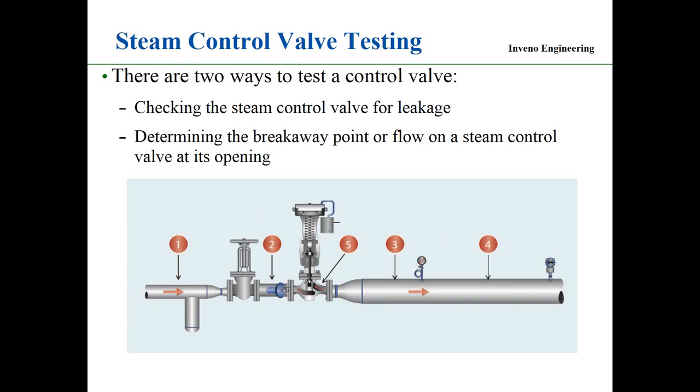Because I'm starting to set up a PID loop. And the PID loop assumes 4.0 milliamp is 0, no flow, and 4.4 milliamp, there is flow. If I have a dead band down here on the PID loop, the valve doesn't start to pass steam until 4.8 milliamps. It does start to cause some issues with the PID loop setting it up and tuning it.